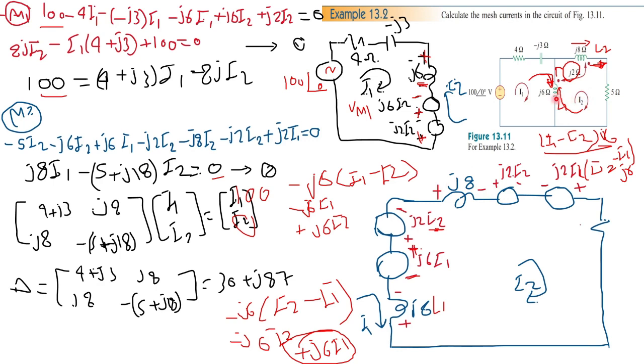And then we have I1 passing through L1. It's entering the coil at the dot. I2 is leaving the coil at the dot. So it's an opposing connection. So it would have a reverse polarity to the voltage drop around L2. This means that it's negative here and positive here. This represents all the voltage drops, with the resistor, of course.